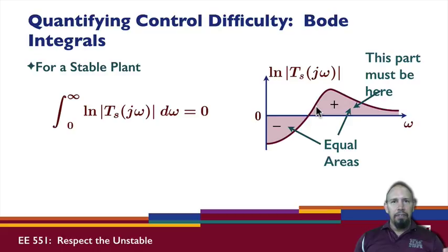So it would be nice, ideally, if the error... So remember, the sensitivity is the transfer function from the reference to the error. The error is the difference between the input and the output, and it basically is an estimate of how well the system is tracking the input. So what this is saying is I can track it well at low frequencies. It does not track it well at all for higher frequencies in these areas.